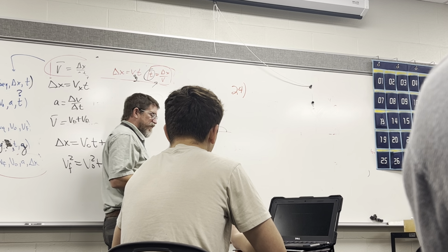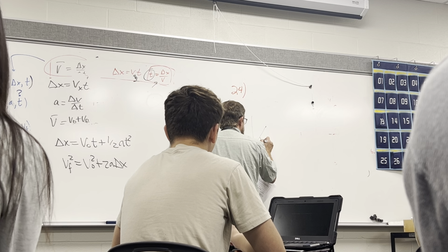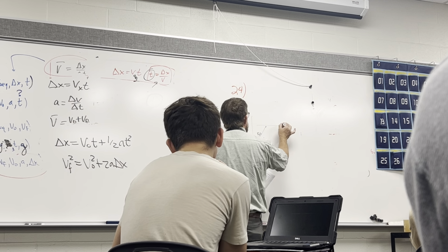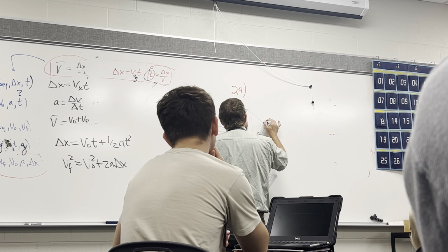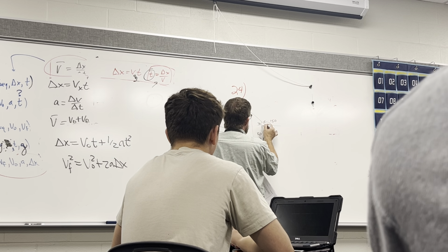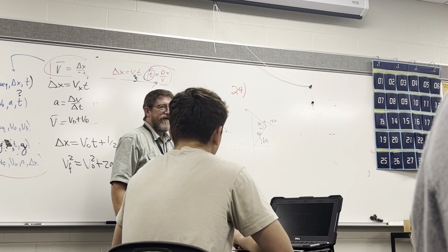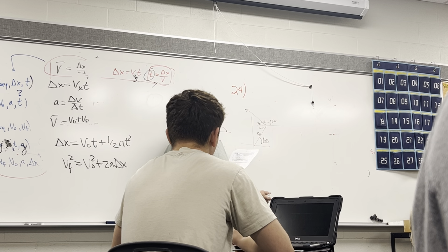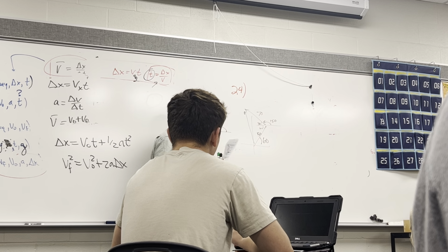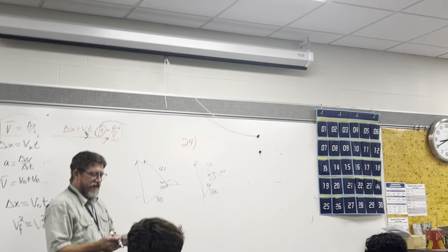Number 2 is 50 meters, 60 degrees northeast. And then you're going to have 70 meters at 150. It's doing a weird thing like that. 150 is 30 here. Oh, this one's also 90, isn't it? Because 30 and 60 is 90. So those are perpendicular. So it's a 50, 70, whatever that comes out to be, triangle. You can double check your answers. This is the kind of thing that I like.